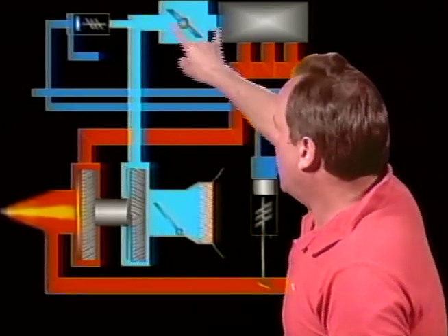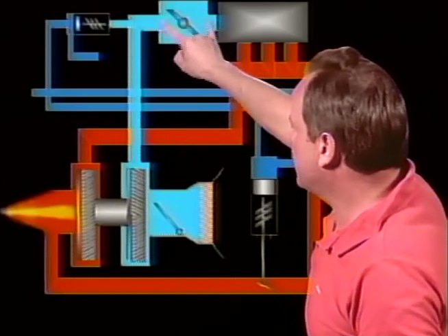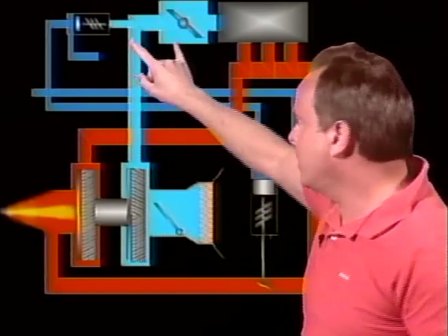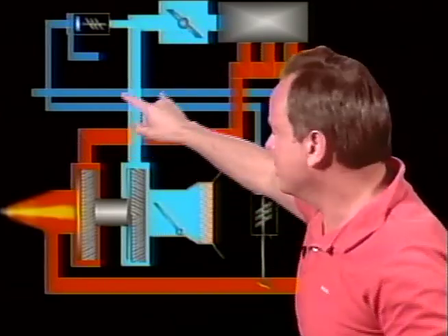This system, the pressure differential controller, also prevents you from having bootstrapping, the turbocharger going up and the turbocharger going down, and the whole engine picking up RPM and dropping off on RPM and manifold pressure, because it tends to stabilize because it maintains that 2-inch difference. So this differential pressure controller tends to eliminate bootstrapping. We'll talk more about that on a question later on.